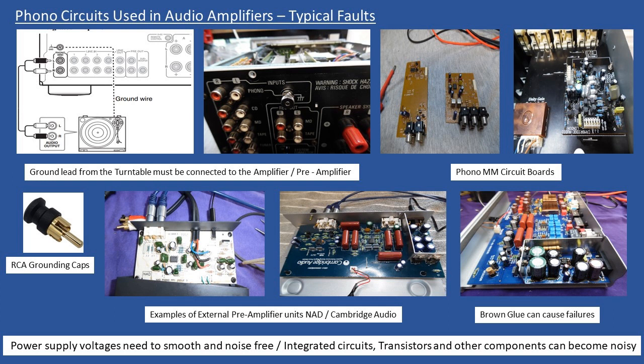In terms of fault finding internally, remember that these phono sockets that you see can also break away from the circuit board. You may have the negative part of the phono input socket broken away because they have mechanical stress when they're fitted, so double check that, and that's why I'm showing these boards have been removed from the amp. Or you may have these plug-in type circuit boards where you can isolate it to the board and then fault find that.